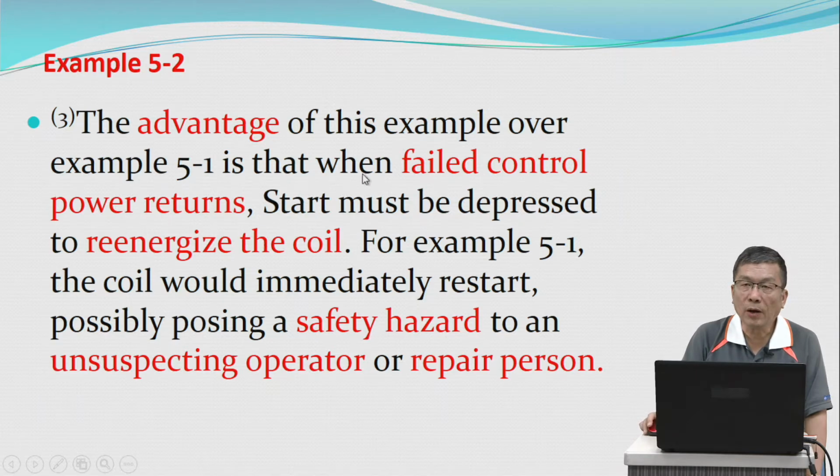The advantage of this example over example 5.1 is that when control power returns, start must be depressed to re-energize the coil. Otherwise, the coil would immediately restart, possibly posing a safety hazard to an unsuspecting operator or repair person.